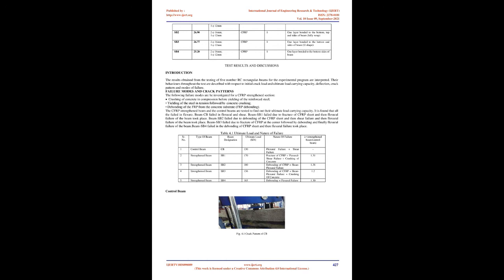vinyl ester or epoxy. FRP composites have proved to be extremely useful for strengthening of RCC structures against both normal and seismic loads. Unidirectional CFRP sheets as shown in Fig 3.2 having cross-section 500 × 1.0 mm are used for wrapping the beams. Table 3.8 shows the properties of CFRP sheet.